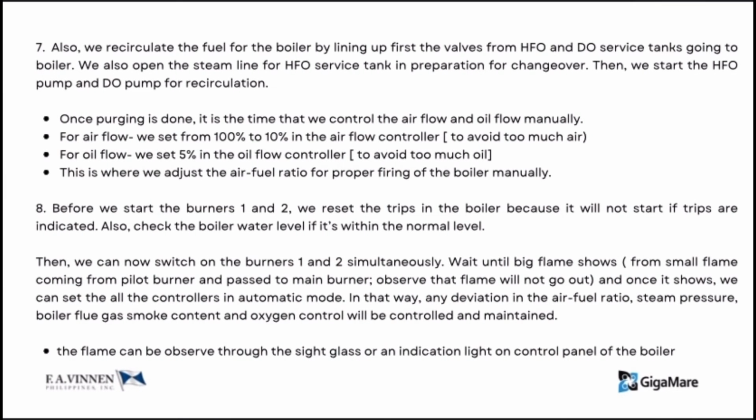So it is important that we first line up all the valves from the HFO and DO service tanks in order to recirculate the fuel in the boiler combustion. And next, once purging is done, this is where the air-fuel ratio comes into action to control the airflow and oil flow and to avoid alarms.